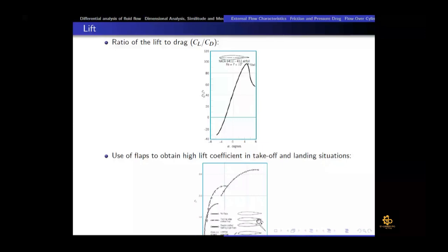But the consequence of putting the flaps more and more in the downward direction is that the drag force would also increase. But it would also come with the increase in lift, which we usually employ, because it is only a small portion on the trailing edge, so it would increase the CL value more as compared to CD.